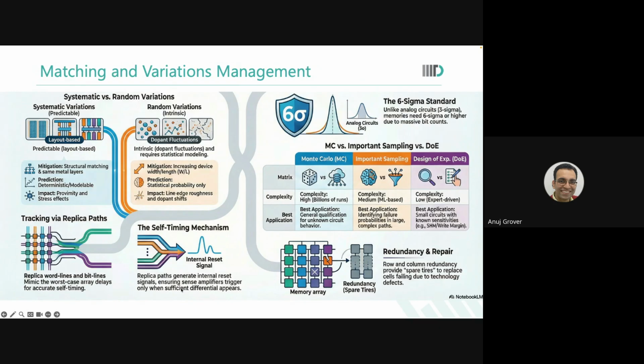What you can say is, okay, in the generation of SAN, I have 1 inverter delay. In the generation of precharge reset, I have 3 inverters delay. By design, this functionality is taken care of. That's what you can do now. It's very controlled, and you've saved on power, and you've improved overall dynamics also. Delays are managed.